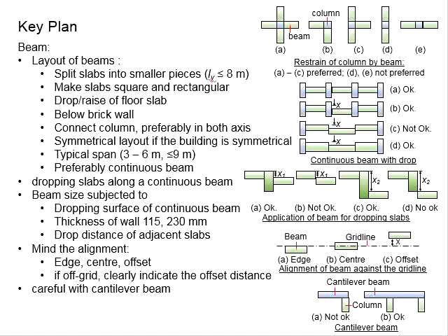Next, you need to consider the beam size. That is another thing that you have to decide. It is normally pre-decided for you to start with the analysis. If the section is undersized, through the calculations you will find some failures due to certain conditions of the loads or certain considerations on the structural aspects. When it is undersized, you will need to increase the size in the analysis later to ensure it reaches the size at which the beam passes in all structural aspects.